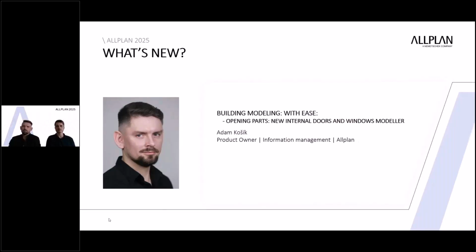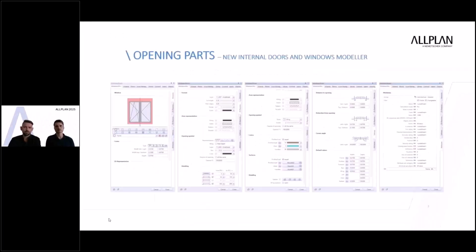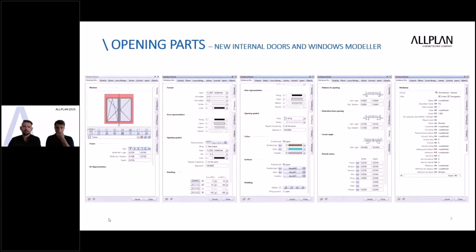So let's go. Up until now, the design functionalities for doors and windows based on the original SmartPart script encountered numerous disadvantages, the primary concerns being performance issues and an inability to modify multiple doors and windows simultaneously. Therefore, in Allplan 2025, we have completely revised and integrated the internal door and window modeler, internally known as opening